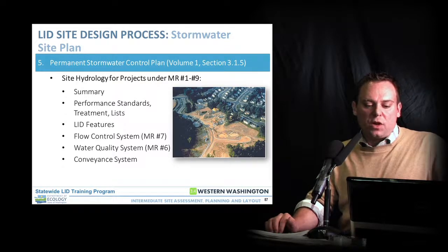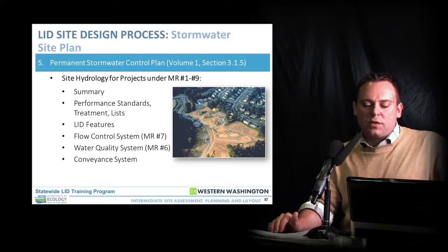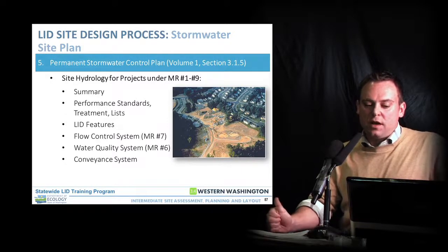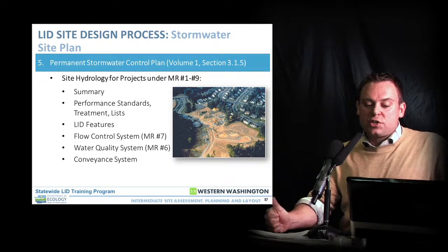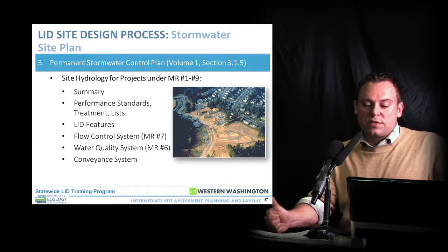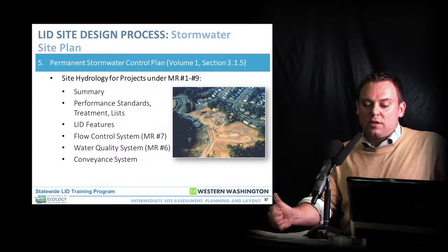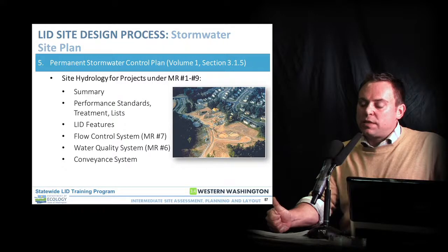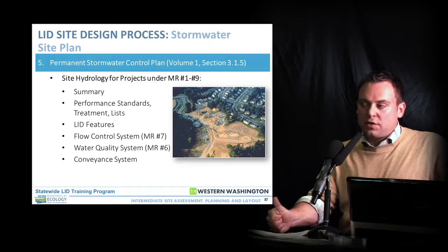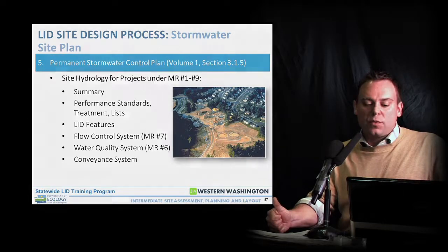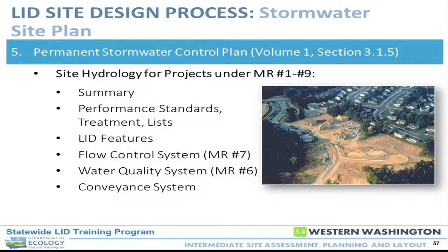So a little bit more on there, just an outline provided in the manual for what is in there. You have the summary, a description of your public or private ownership, so describe what's in there. Areas that you're protecting on the site need to be demonstrated. You need to show drawings of all your on-site stormwater facilities. Identify where you're retaining planted trees and how you're doing credit calculations based upon that. Again, you're also going to do your infeasibility documentation in this report, and then provide all your design details, figures, and maintenance instructions for how to maintain these facilities that you're going to build.